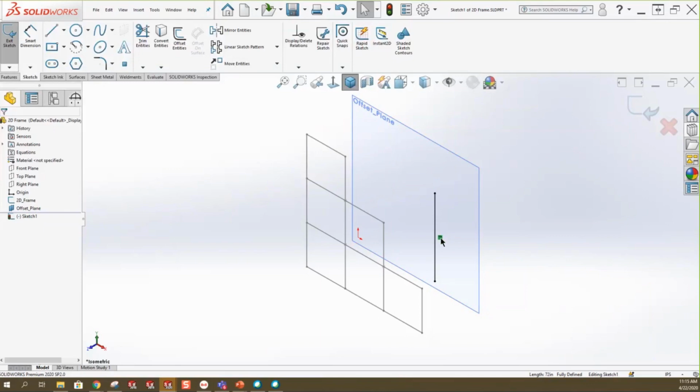So say I had a hole in a plate and I wanted to project that onto another face, convert entities. It's beautiful, right? But here's the problem. Again, any changes I make could adversely screw this up. So if I get rid of this line, it's going to go, well, I don't know what I live on anymore. You've got to fix me.